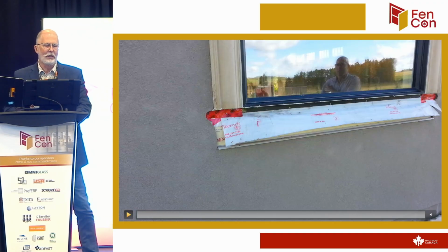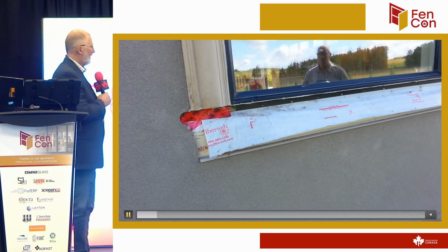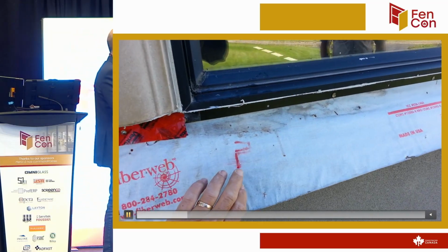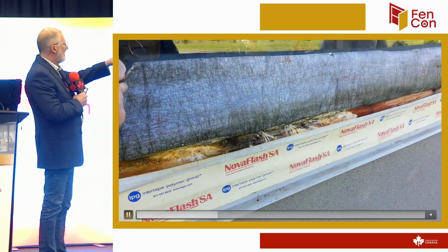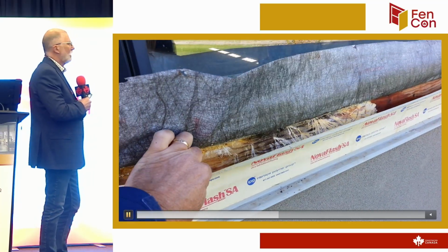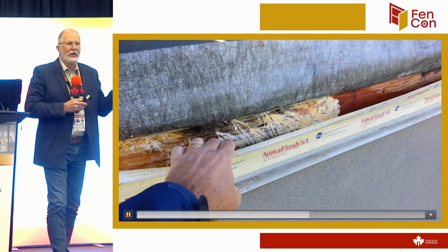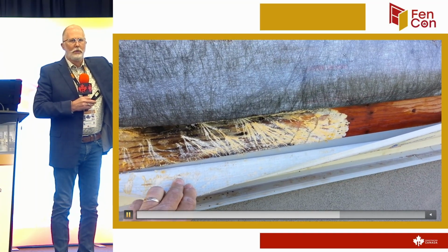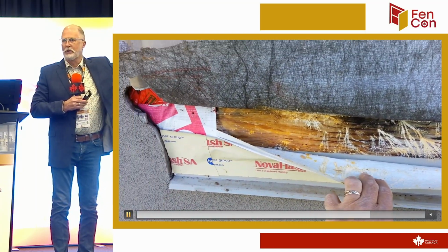Now, if you look at something like this, one is open. This is a pretty typical construction you would see. Where's that water coming from? It's coming out from the rough opening. Why is it getting in there? Well, in this case, it was coming into the soffits. It was wind-driven rain. It was the exposure that was being experienced.